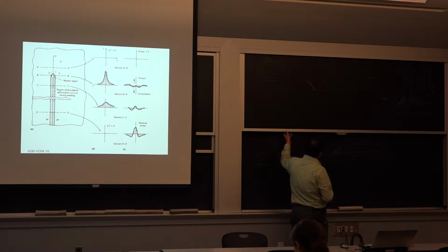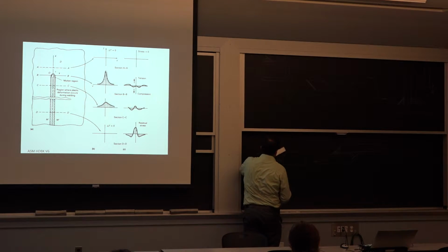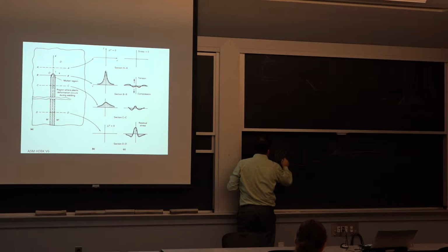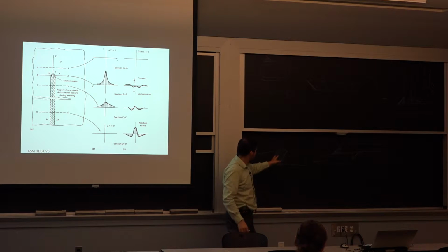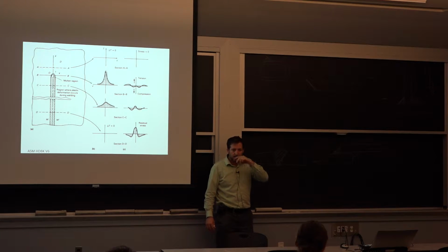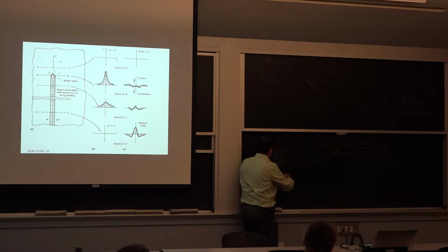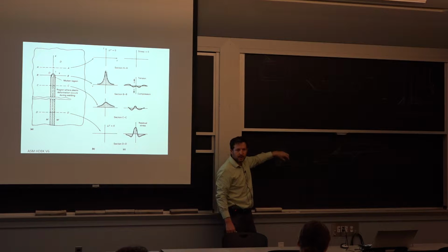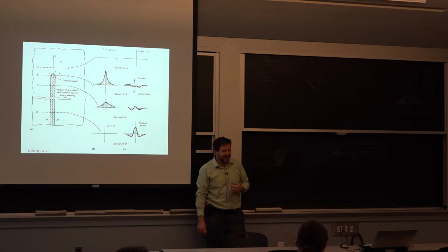It's easier to see on a butt joint. So we'll go back to this one here and assume for now that we're welding this entire zone all at once. So this becomes melted. It's very, very hot, and it cools. So when it cools, this zone is going to shrink as opposed to the material surrounding it. So there are two things that happen. The first one is distortion. It will bend this way. And the second one is internally, the reason it bends is there's a driving force. There's tension here on the surface that needs to be accounted for.